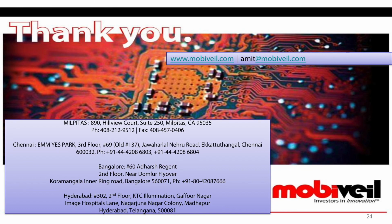Do you have the solid data to support this? Oh, yes. That's what the Flash characterization platform does. This platform actually does that. So you do a write and then you do it multiple times and then you read back. Then you analyze how many bits got flipped. Yeah, error is still there. Of course it is there. That's the biggest problem you have today in Flash, because as the parts are getting denser and denser, there are more errors per sector. So this is a major problem.